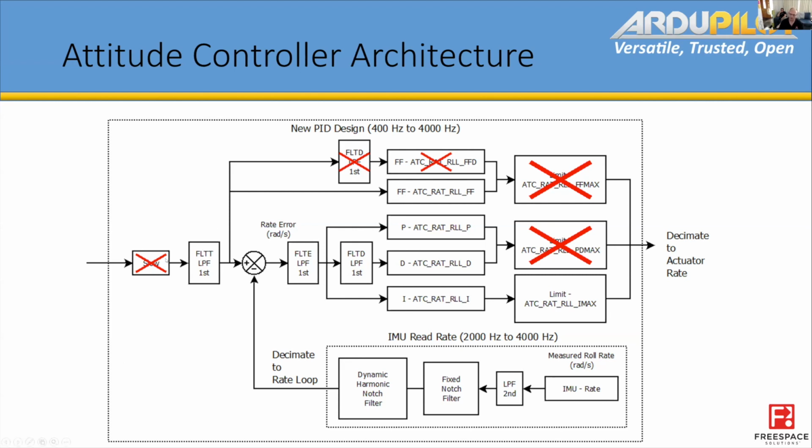And this is the target filter, and everything comes from the rest of the attitude controller and the EKF and all those other noise sources I was talking about. This just gives us an extra pole to reduce that high frequency noise coming through. As I said, there tends to be a bunch of little step noises, like little steps that create broadband noise coming through. But then there's also the unfiltered noise. It's got a low pass integrator on it, effectively coming from the EKF, but that's effectively unfiltered noise. So being able to chuck this target filter on really helps reduce that.